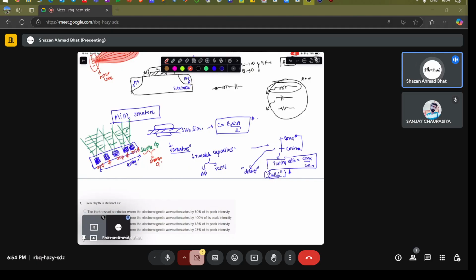What you can brilliantly do is steer the direction of the microwaves, just like if you are using a torch and steering it in different directions with the help of your hand. But here you don't have to move your torch. You just have to give a different phase to the signal, and that phase can be changed with the help of these delays. That is a very beautiful concept.